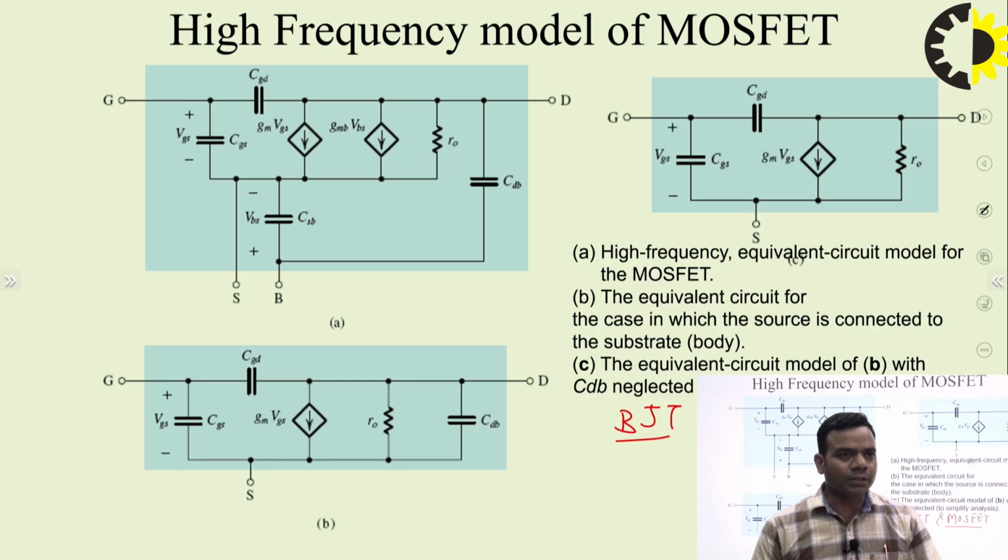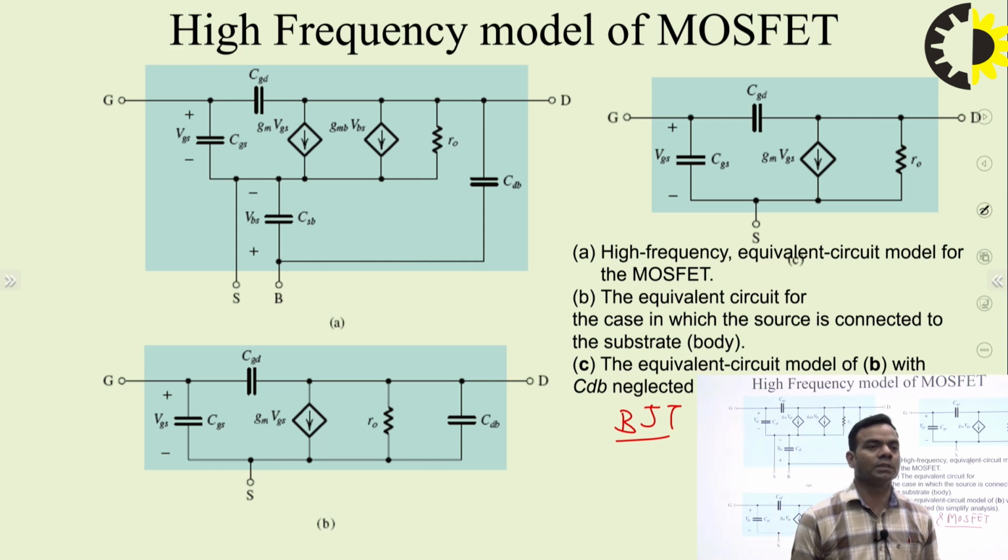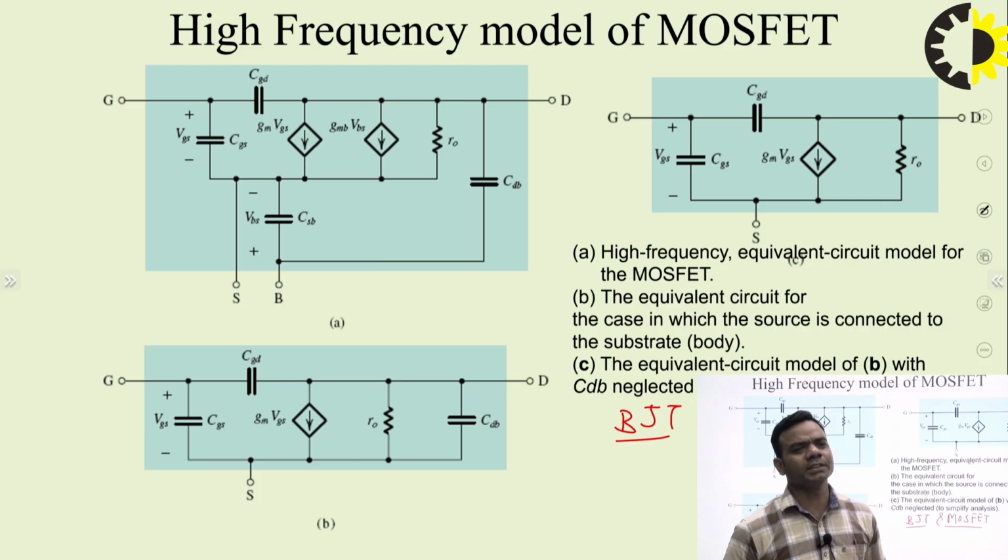One thing that we also remember about MOSFET is its input impedance is infinite. Practically it is very large. So due to that, no current flows into the gate. That means from the input side, the current will be 0. In other words, I can say that input current is equal to 0.